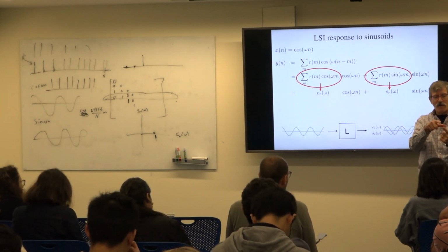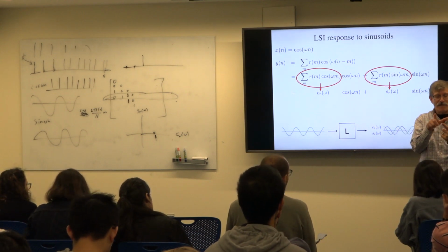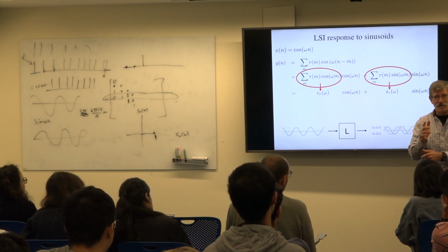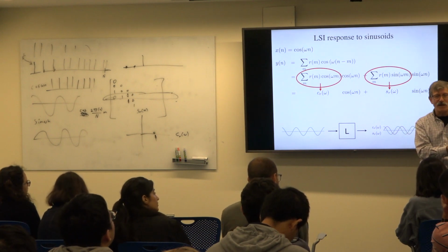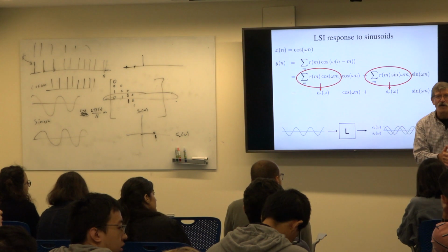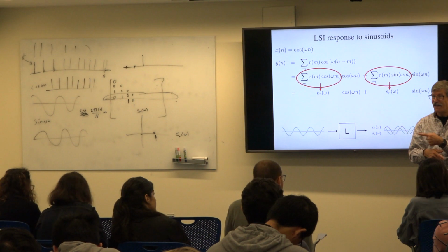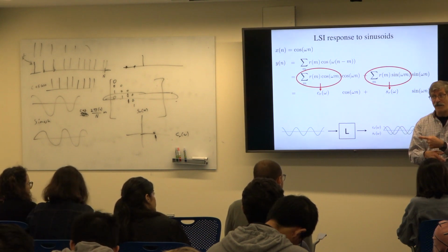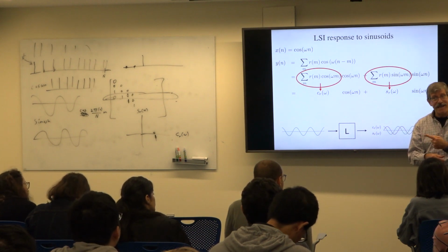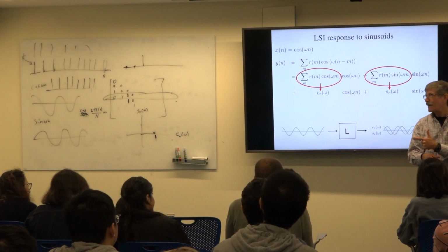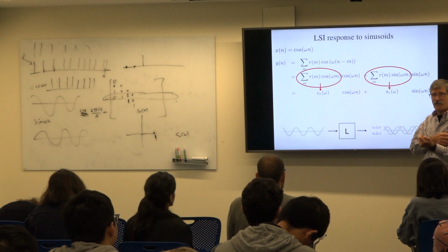We'll talk about that. But if I have frequency 0, that's cosine only, sine frequency 0, frequency 1, frequency 2, frequency 3, frequency 4, a bunch of frequencies, and I call those the columns of a matrix that re-represent the signal, and re-represent it because of math we already know. Because if it's a cosine matrix, then you take our signal, you multiply it, you're just rotating it. You're re-representing it in a new coordinate frame, but you're not losing any information. That's where we're headed. Having done that, we can take any signal, rotate it into sines and cosines, use this math to say systems treat that really simply, and then rotate back. That's kind of the outline of